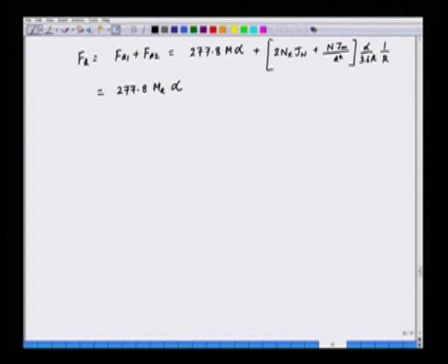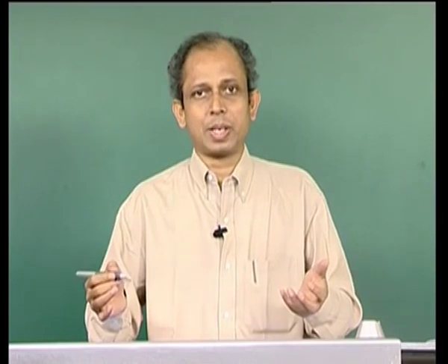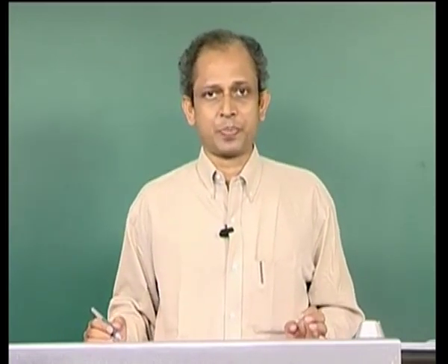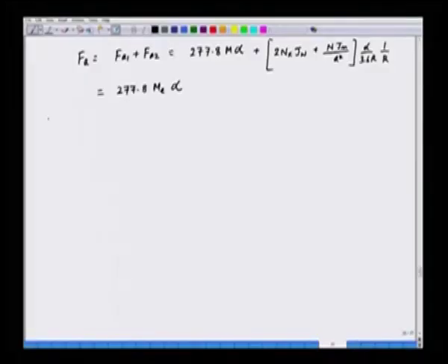So, we can simplify that the actual mass of the train is not Me, it is just the weight of the train or the mass of the train in kg or in ton. Now, the effective mass includes the rotating part also. So, this effective mass Me is 10% higher than the actual mass. So, this is basically for the acceleration which is the horizontal plus angular, and then we have other tractive efforts also. So, let us see the other tractive efforts.